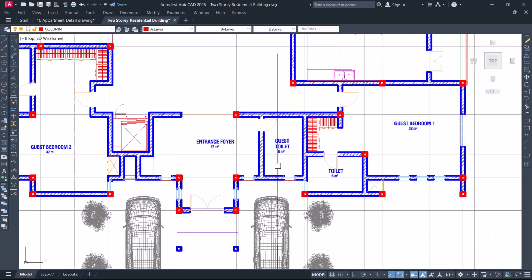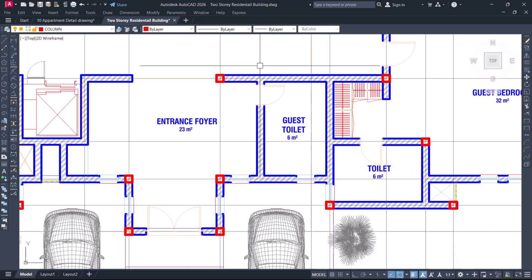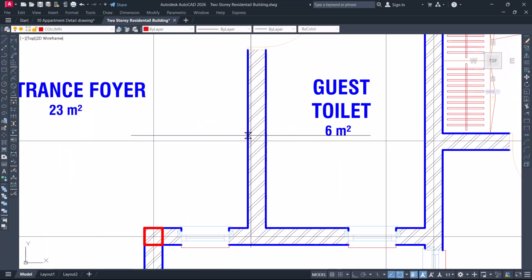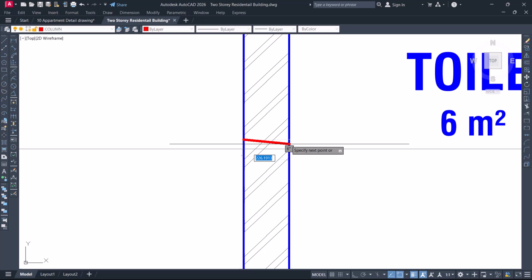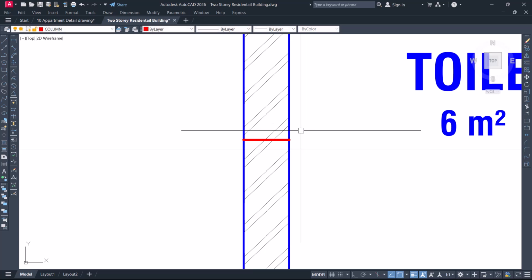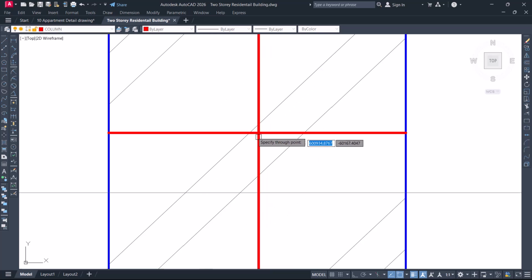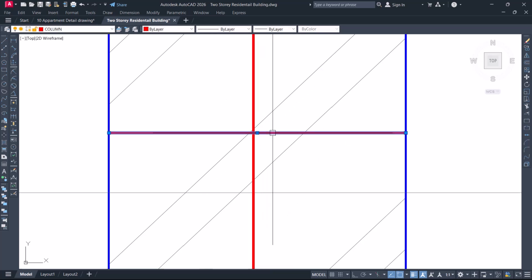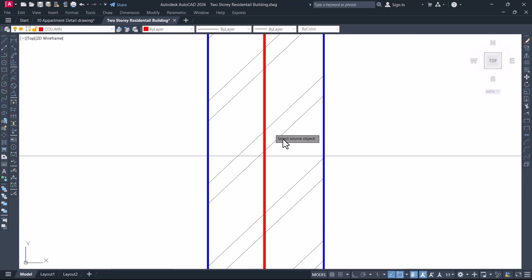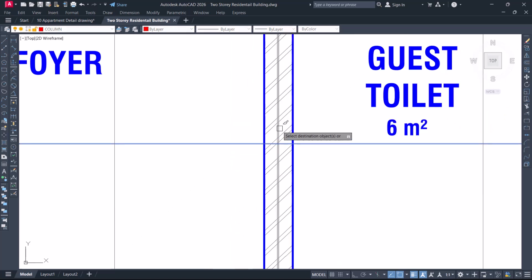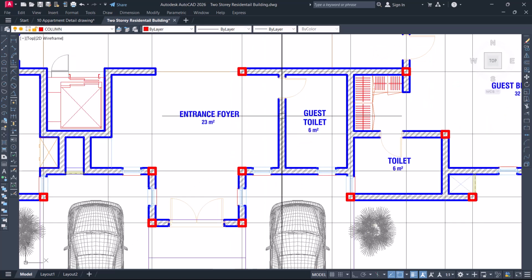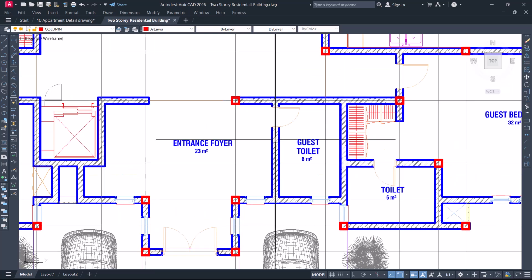So let me just break this panel with a beam. So I'll place a grid line here. Yes, it's okay to leave it as 29, but let me just break that. So I'll just click on this and then type XL enter, V enter, and place a grid line here. And make sure you convert it to a grid line layer. I'll remove this one, then MA enter and match this to this. Okay, that's fine. No need for us to place any column here because this beam can just support itself on the beams which we have below them.